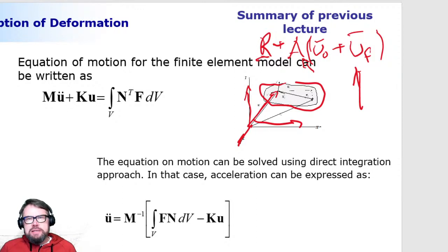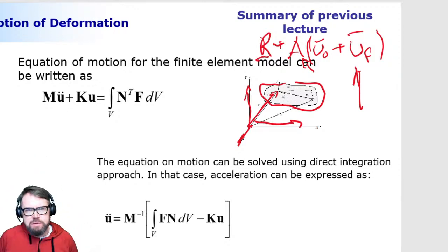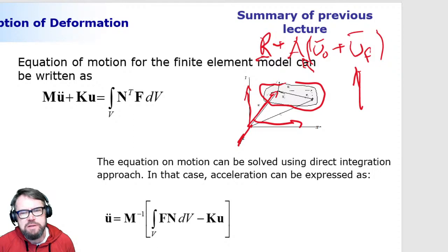And we concluded that the easiest, definitely the easiest way to describe the u bar f is to use a finite element procedure. In a finite element procedure, you're discretizing your structure by using something that looks like a fishing net. What that stands for is elements. A single element is not yet an acceptable solution, but once you keep adding the number of elements in the finite element method, you are getting a better and better solution.